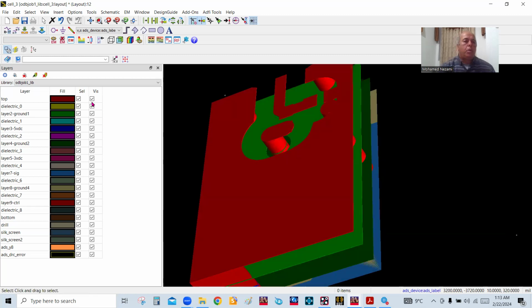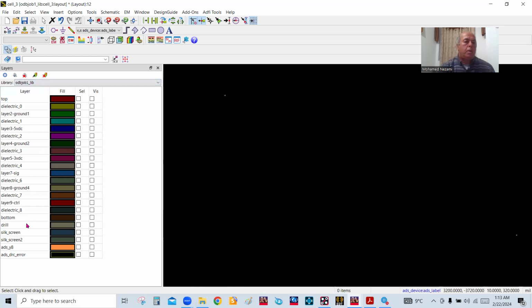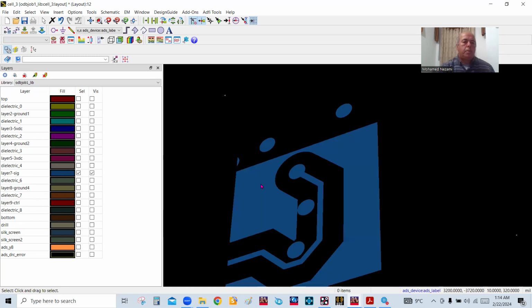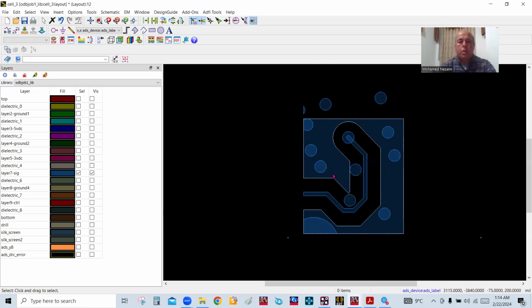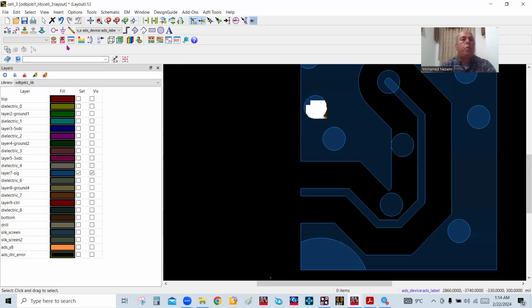And so what we will do is let's turn all of these off right now. Let's turn 7 on again here. Oops, that's the dielectric. So we're gonna put 7. Okay, here it is. So what we're going to do is I'm gonna put an input port on this. So we're gonna go to signal 7.